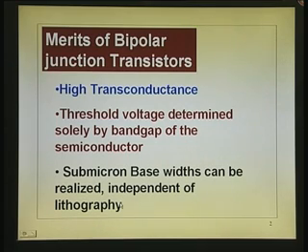Then we also discussed that submicron base widths can be realized independent of lithography. We have that advantage because you do not need to use lithography to control the base width. It is decided by the base diffusion and the emitter diffusion, if you are talking of diffusion, or it is decided by the epitaxial layer thickness or by implantation doses. So it is controllable that way. You do not need electron beam lithography to get a 0.1 micron technology base width.